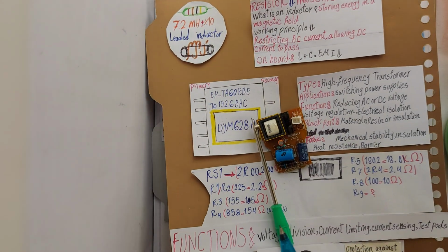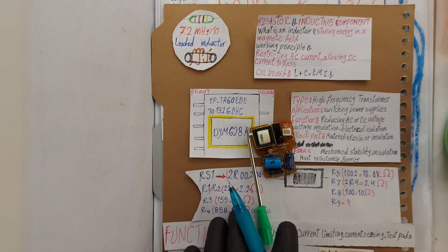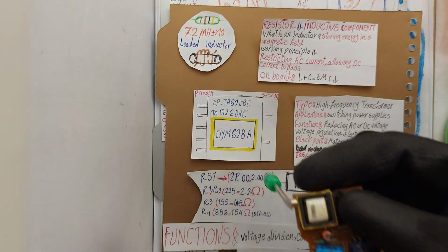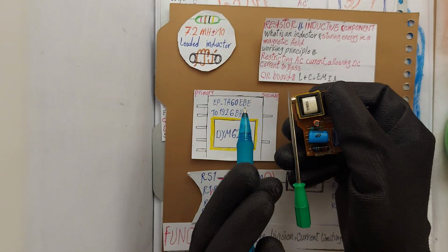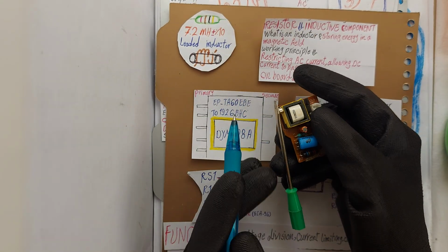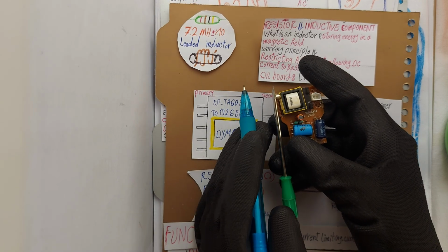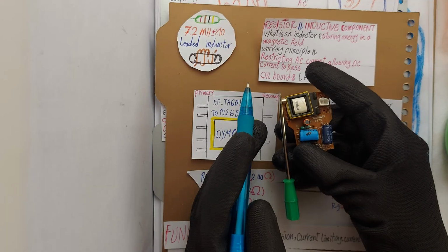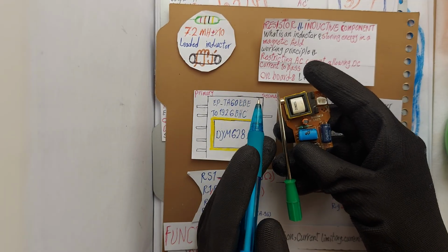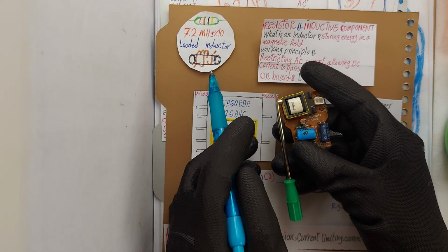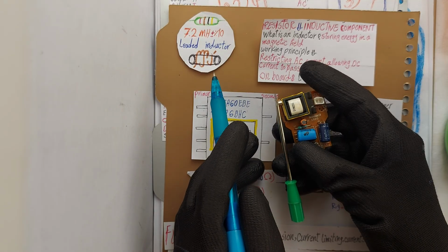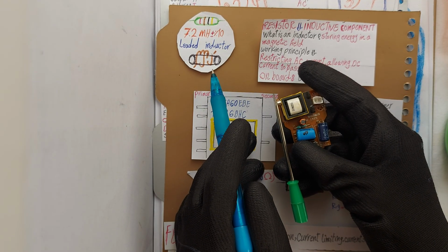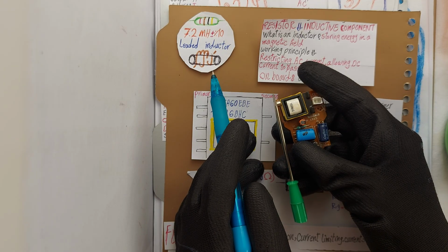We've reached the inductor, as you can see right here and here. Specification: 7.2 mH with 10% tolerance. Inductor type. The inductor here appears to be a leaded inductor. This type typically consists of a coil with a ferrite or air core, as you can see here, with wire leads designed for board connection. It's likely a single coil inductor, as only one coil is visible.